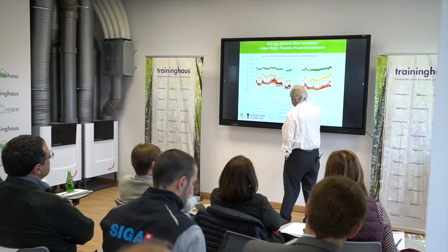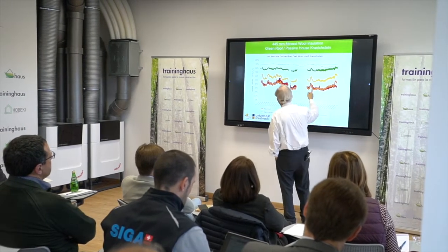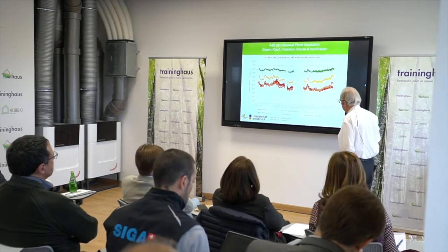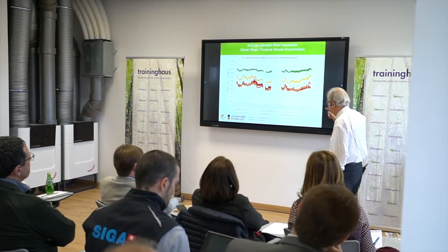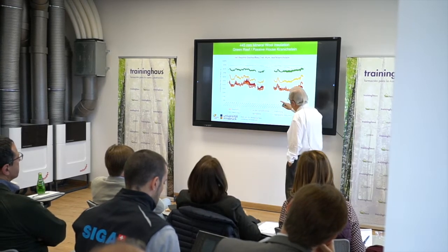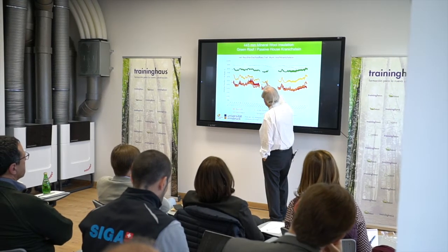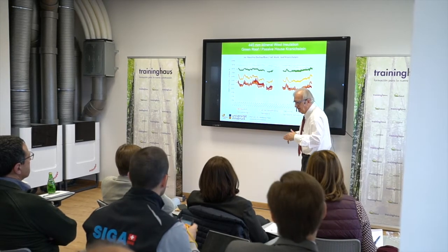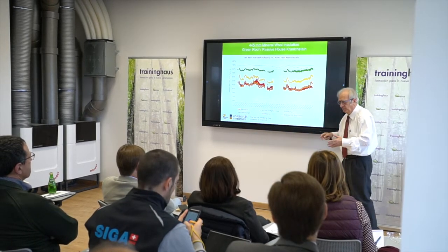They are in the range between 30 and 50% during winter in this ventilated building. So that's, I think, completely okay, so no problem with that. And then we see, of course, that the relative humidity in the construction will be higher when we go to the outside. Now, this is completely normal.